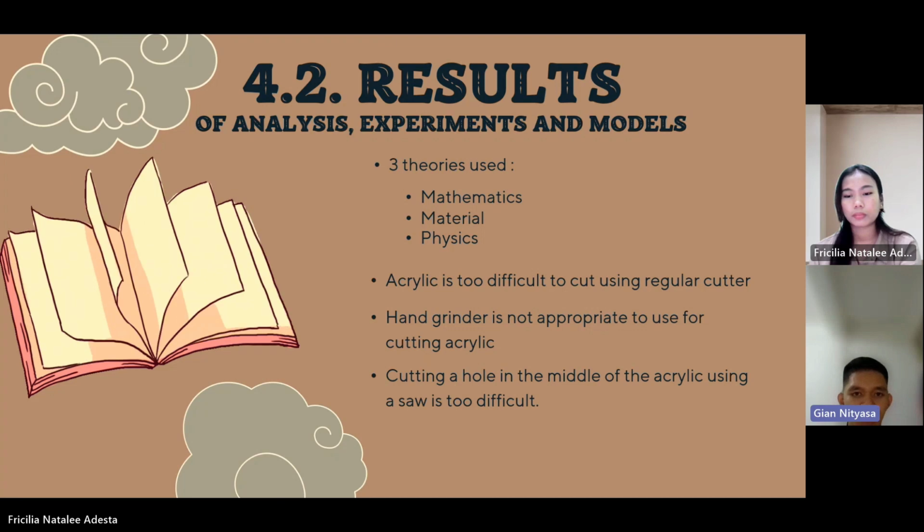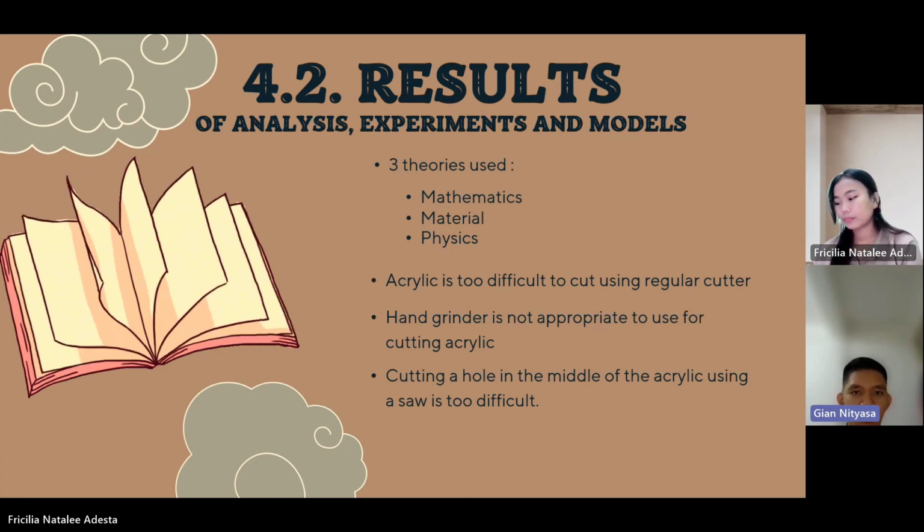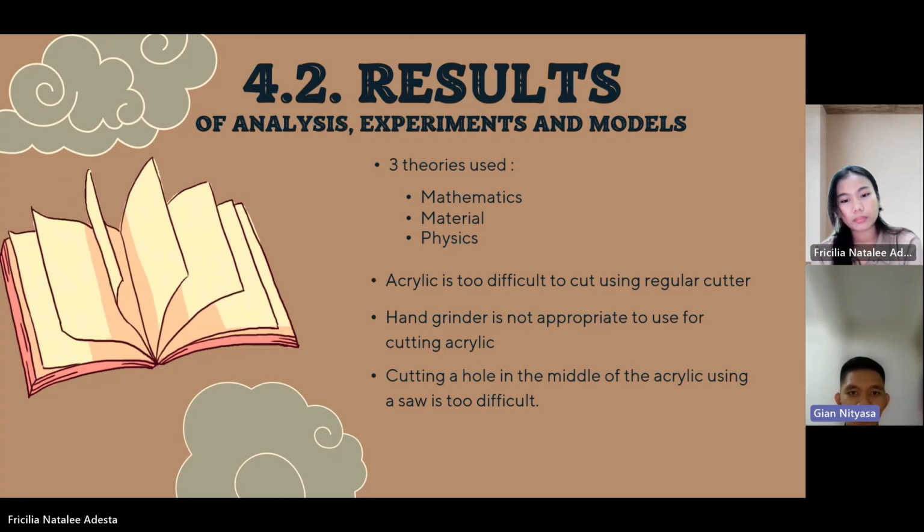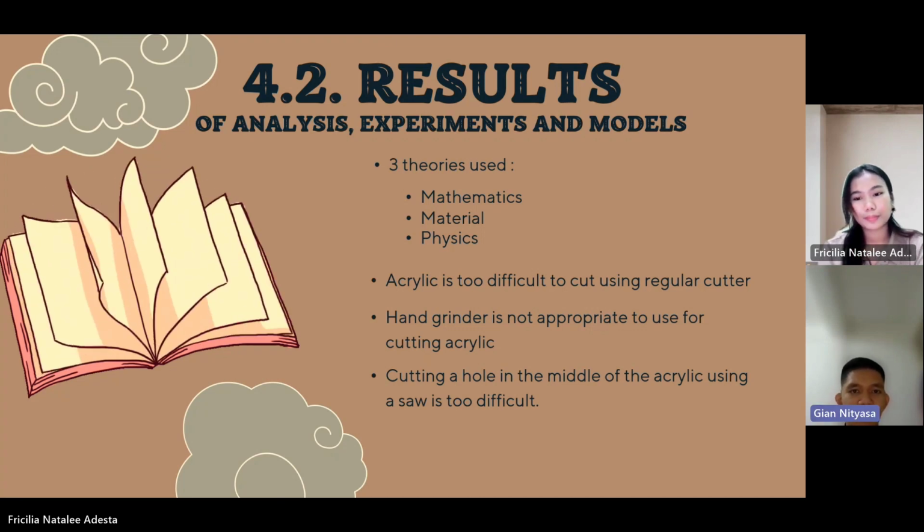And so after that, we did some experiments in cutting the acrylic. We used different tools: a regular cutter, a hand grinder, and a drill machine. For the regular cutter, we found that cutting acrylic with that tool is quite difficult.